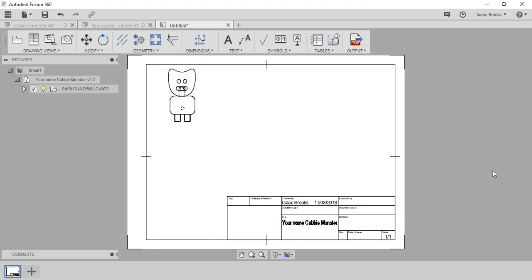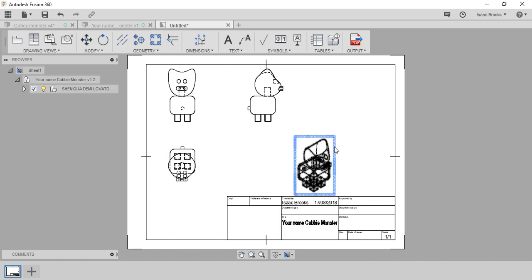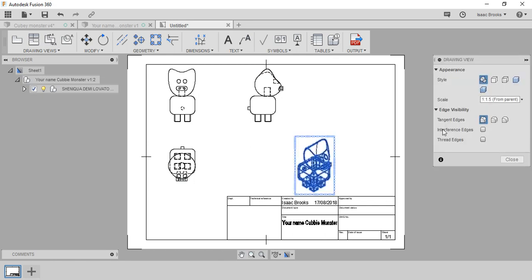The color will disappear. We don't need the color for our measurements. We will put the color into one isometric image, not the orthographic. This is the orthographic projection now. We do a top view and a side view, and then finally our isometric view. Once you're happy with that, right click, go OK. Now I'll go back to wireframe, double click on that blue line and change it to this one here, which will color it in, but you'll still see the hidden line. Actually, isometric, I'll change that just to the shaded view.